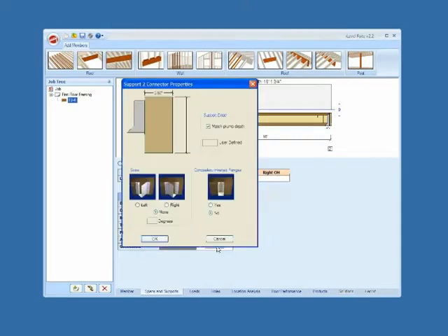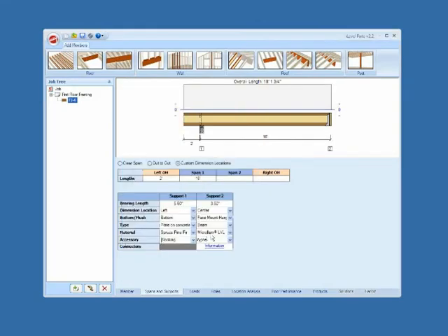Whenever you have a hanger connection, you get this information link, and this allows you to specify if, say, your supporting member is shallower than your joist. You can put that in here. You can also put in a hanger skew if you have one. Also whether it's concealed flange or not, and this is going to size the appropriate hanger for you. So the more accurate you are with this input, the better off everything is.